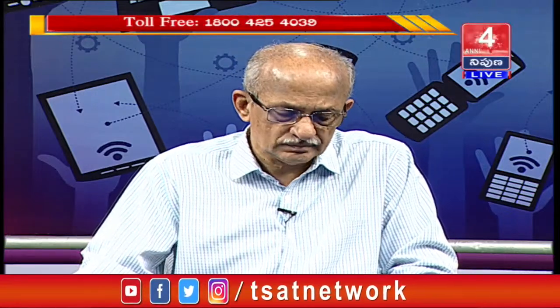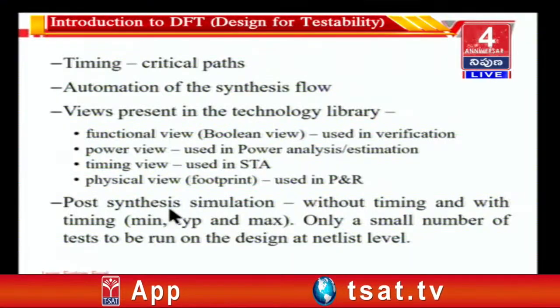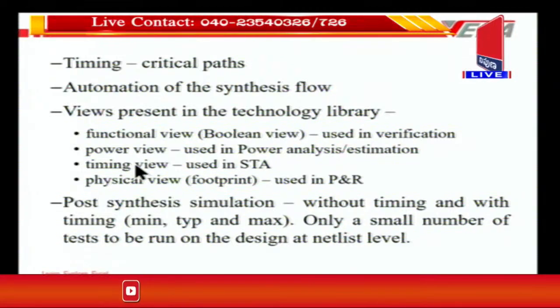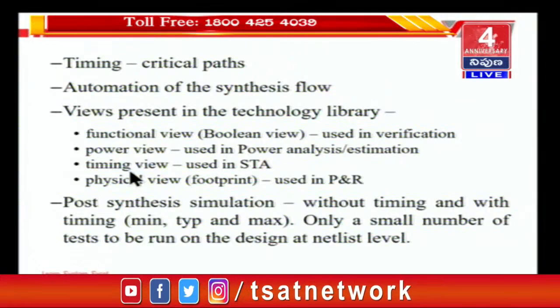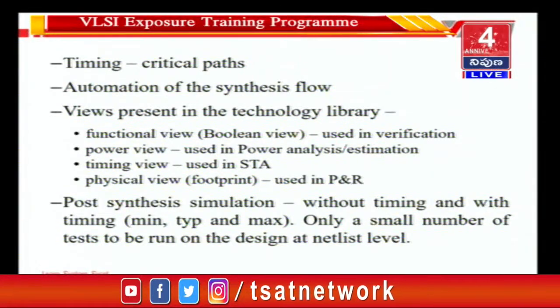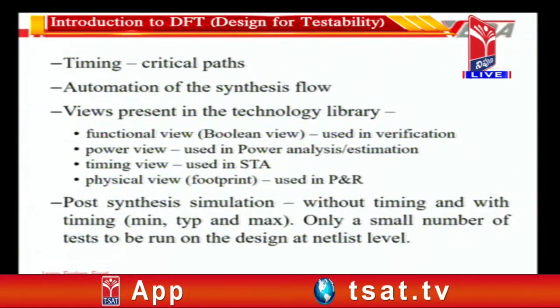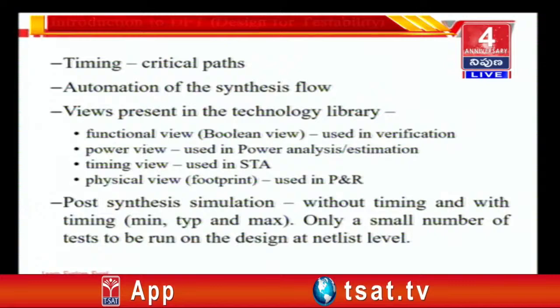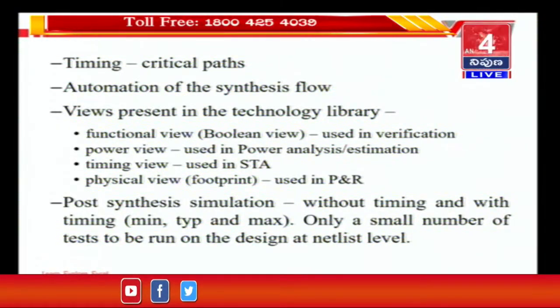They call it a footprint or the physical view of that particular cell. Now, in this particular slide which I am showing here, I mentioned that gate level simulation is extremely slow compared to RTL level simulation because of the number of details that are involved in gate level simulation, and the more the details, the more computational power is required. So the time required for gate level simulation is pretty large compared to the time required